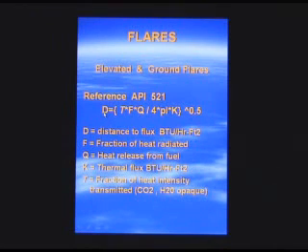D is the distance from the flame source. Tau, the T-value, reflects the attenuation of the flame due to either water vapor, CO2, whatever's in the air. F is the fraction of heat radiated from a combustion process. For heavy hydrocarbons, that can be on the order of 0.2 to 0.3. For light fuel gases, 20 molecular weight in that area, measurements have found that you can use like 0.08 to 0.1 flame fraction.